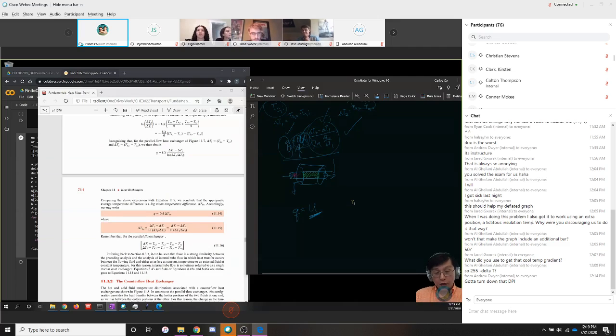So this U value, your overall heat transfer coefficient, involves the individual H values for the inside and the outside, as well as another resistance to heat transfer associated with the thermal conductivity of the shell wall material and the thickness of your walls, of that pipe that's separating the inner and outer flow. So the thickness of that pipe essentially there.